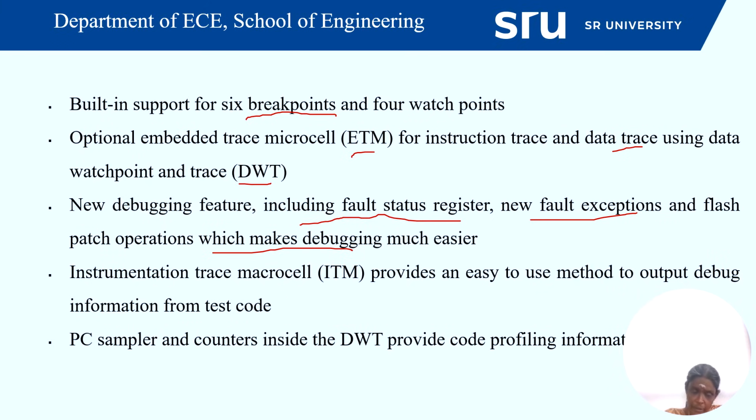And one more thing, it is used for advanced debugging without halting the CPU. So CPU speed will not be reduced, nor will it intermittently halt. CPU operation will be continuously moving on. Therefore it is faster than UART, the universal asynchronous receiver transmitter, which is a serial communication interface only. And minimum code overhead.